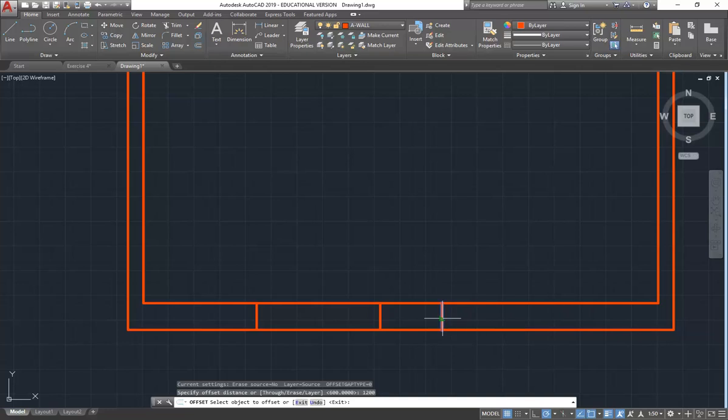So what happened there, do you know why it went the wrong way? Yeah, and the thing is, I actually had the cursor on the right, but the problem is object snaps on, so it snapped to a point on the left, even though my cursor was on the right. So there's a bit of a trick there, just move it away from any object so it doesn't snap to them. So there I'm clicking to the right, but not on a line or anything.